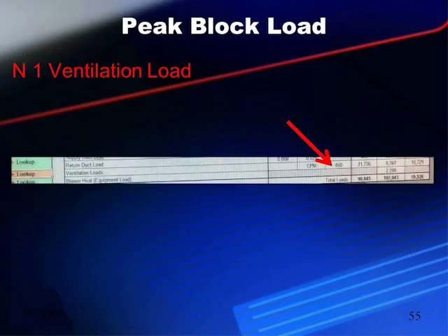Well, if you followed me all the way to here, then you got it 100%, because this is it. Once we're done with the ventilation loads, then we fill them in on the N1 sheet and we get our total loads. You can see them down there on the bottom. And what you have then is a complete sheet on the N1 that you can print out, and you have a load calculation that you can turn in.